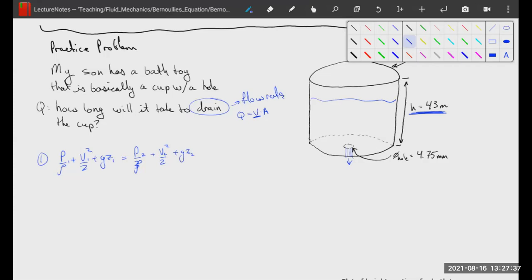So if we keep it simple, then it's easier to do the algebra later. Okay, so we have this. Let's do our assumptions. Oh, sorry, let's assume actually gauge pressure first. Now you don't have to write this down, but it's a gesture of goodwill towards the graders, right? You're telling them, hey, I'm using gauge pressure. I know it's probably fairly obvious I'm using gauge pressure, but there's zero ambiguity here. Gauge pressure, B, density is equal to a constant.